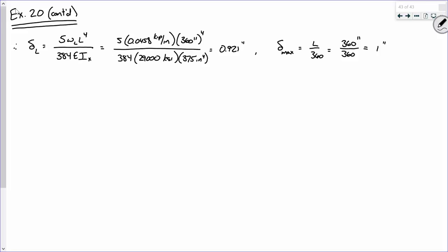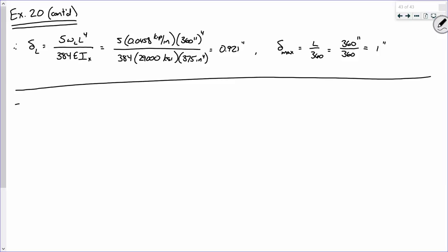That's true, and we brought that up before. You can account for dead load deflection by cambering your beam. Remember, you can bend it upwards, sit it down, then set the dead load on it, and then it sits flat. The live load is the only deflection that the user or the occupant is going to notice. Does that make sense? That's a good question, though, and that's something everybody should be aware of. Everybody good? Okay. The only other thing I want to do is check compactness.